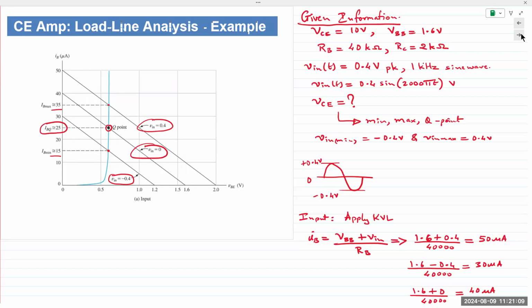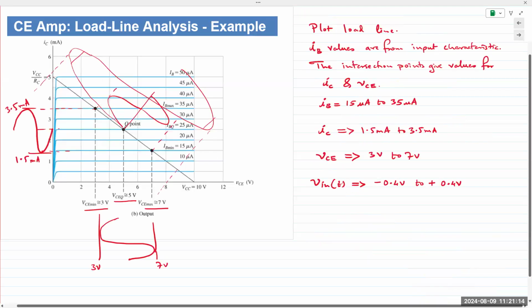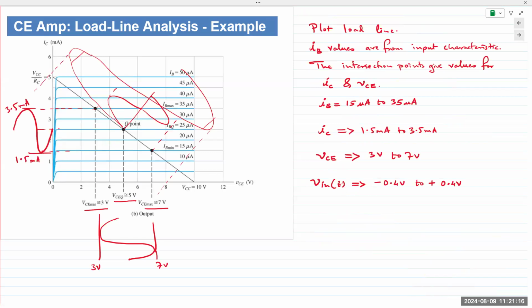Okay. Right now, we can get this to work because we are saying our Q point is fixed right here. If you apply 25 microamps input, then we would obtain 2.5 milliamps at the output, meaning the transistor curves are telling us that the beta value for this transistor is 100. If it was 200, then for applied 25 microamps, our output would now be, what would it be? 50.